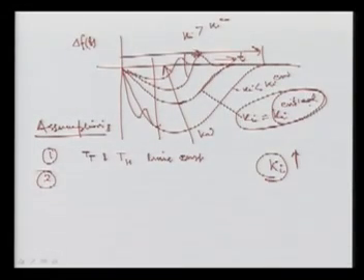The second assumption that we made is that the speed changer response was assumed instantaneous, meaning it was thought that the speed changes, that is your governing system, happen instantaneously. Whenever it is required, suddenly it is given, but that is not always true. Third, we assume no non-linearity in the equipment such as deadband. What is deadband? You can see here we are having some deadband, and then your machine is operating. So this is your deadband. We have neglected all the deadbands, the non-linearity in the equipment, in this analysis.